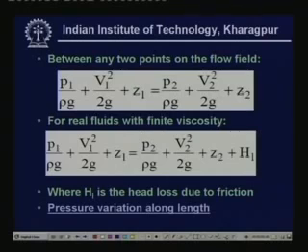And as I was mentioning, for real fluids the flow is not inviscid, that means viscous effects are there in real fluid. So, you can modify Bernoulli's equation by including what is known as a head loss term. So, this is known as modified Bernoulli equation. That means it is nothing but Bernoulli equation with provision for viscosity by including head loss term. So, in this expression all these terms are known to you. One additional term is HL, which is called head loss. So, now let me show the